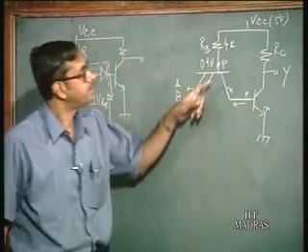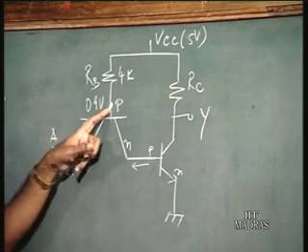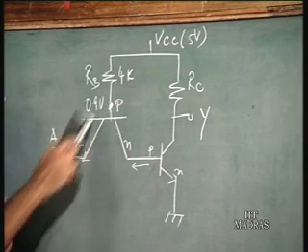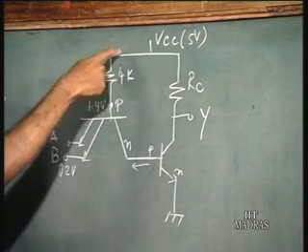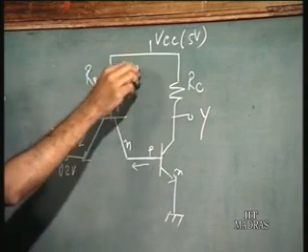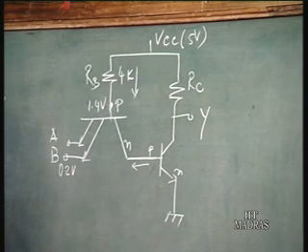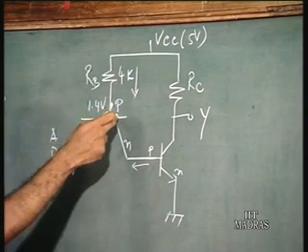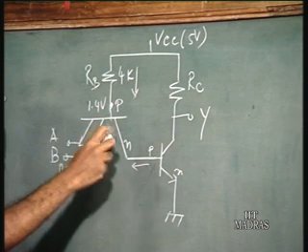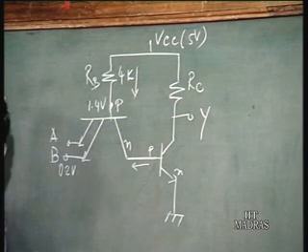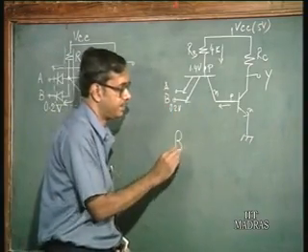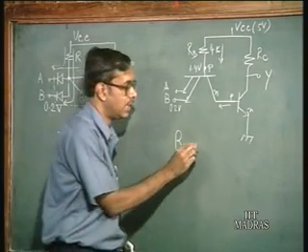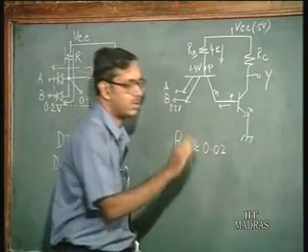Now again, you see what is happening is this voltage is around 1.4 volts now, say. If this voltage is 1.4 volts and this is a 5 volt supply, a current will flow into the base. So there is a base current for this transistor. Now the beta of this transistor is very low. What does it mean? In fact, these transistors are so designed that the reverse beta of this transistor is made very small, about 0.02 or so.